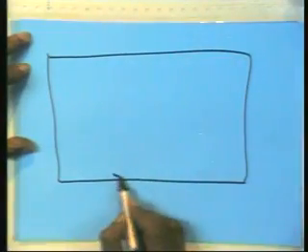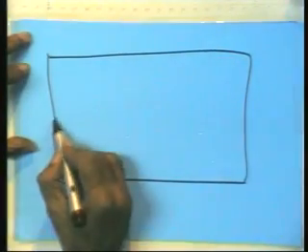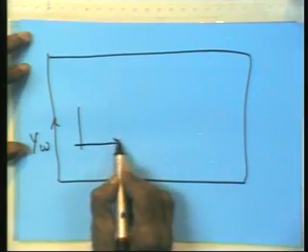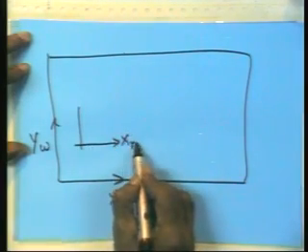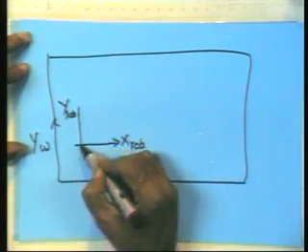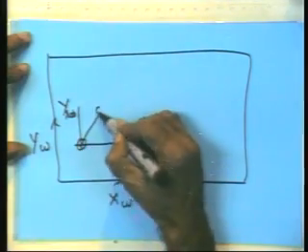Now, that X, Y, orientation which you capture: here is the world and here is the XW, YW. Using the robot as a measuring device, in all probability you would have captured that information in the X robot, Y robot coordinate frame fitted to the robot base.